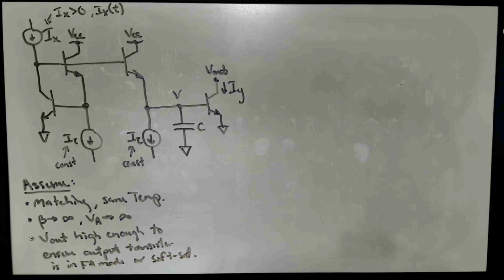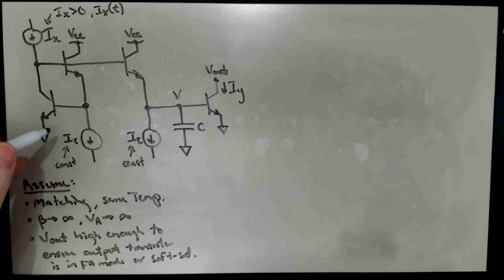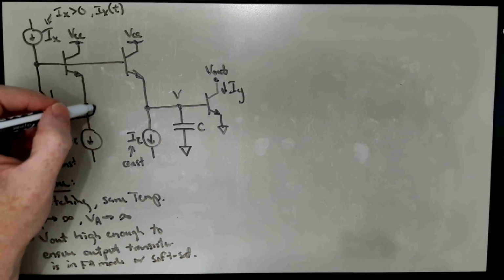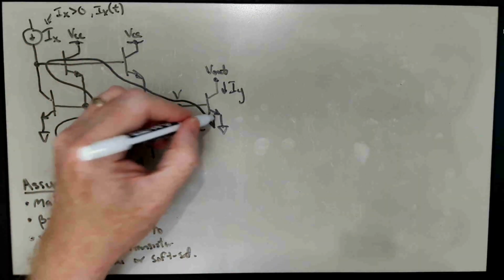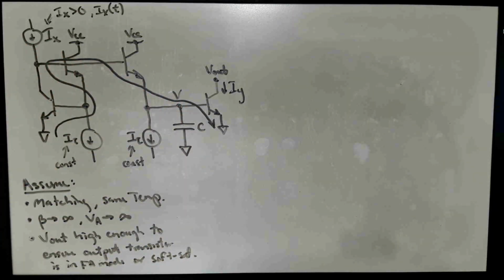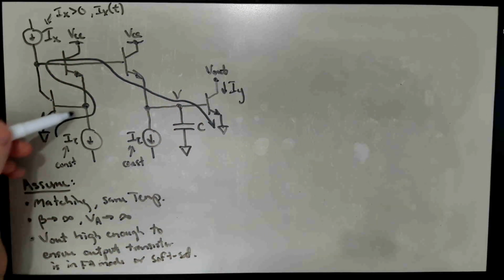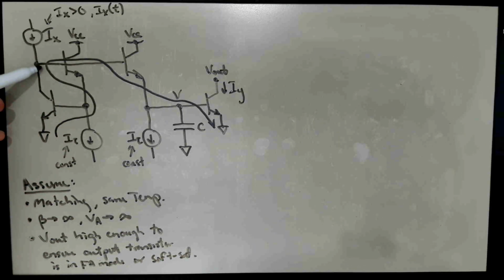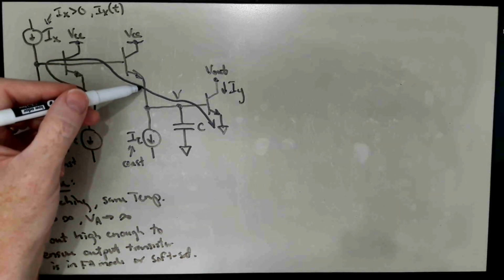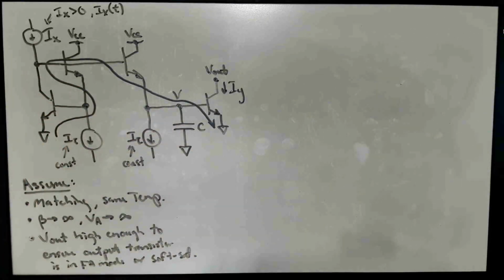And the question is, do we see this translinear loop in this picture? Well, there's a twist in it, but we go up here, down, and back down to ground. So the answer is yes. So we go up one base emitter rise, up a second base emitter rise, and then we go down one base emitter drop, and then we go down one base emitter drop back to ground where we started. And so our circuit does have that translinear loop in it.